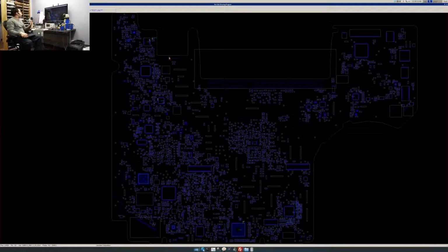So there are 4 possibilities as to why this is not working. The battery is bad, there's something wrong with the battery indicator, or the connector for the battery indicator could have some crap in it. There's something wrong with our U7000, or there's a short somewhere around the U7000 area, or it's the SMC. So to find the short, I decided to inject 3 volts into that line.